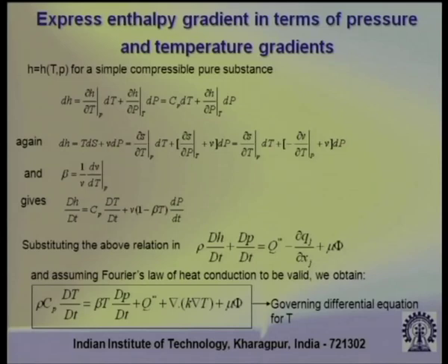All these equations we have derived by using a common synergy. We started with the Reynolds transport theorem and expressed all the terms as either volume integrals or area integrals. Wherever area integrals appeared, we converted those into volume integrals by using the divergence theorem, and then combined all those terms in the total integral expression and obtained a differential expression from the integral expression by considering the choice of the control volume to be arbitrary. That is the general principle that we have followed.